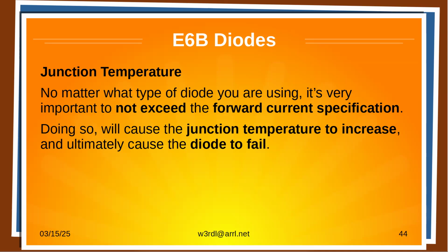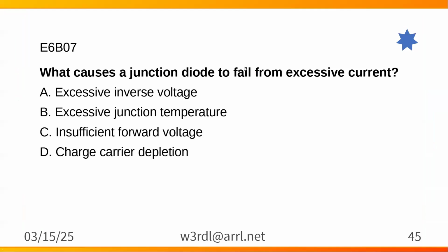So if you've got a high power, high current device, normally it would have some kind of a heat sink or something to keep the temperature down, because you got to maintain the junction temperature below a certain value or this thermal runaway and fails. Whether it's a diode or a transistor, it's the same problem. The smoke escapes, yeah. Well, they don't always smoke, they just don't work. Although I've had them pop.